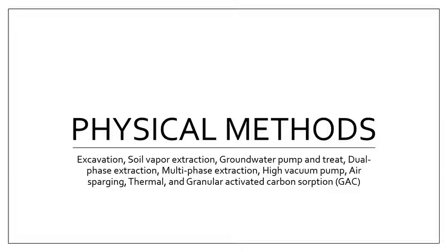Physical methods involve the physical movement of your contaminated phases, like excavation, soil vapor extraction, groundwater pump and treat, dual phase extraction, multi-phase extraction, high vacuum pump, air sparging, thermal, and granular activated carbon sorption.